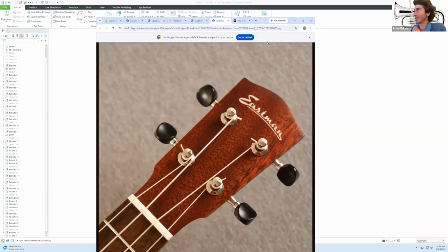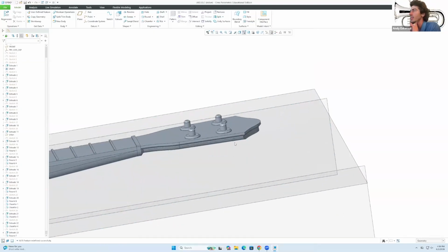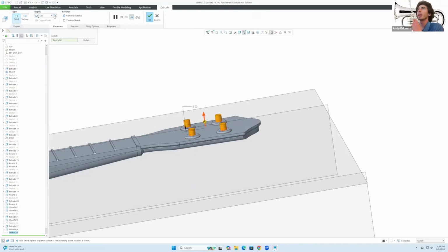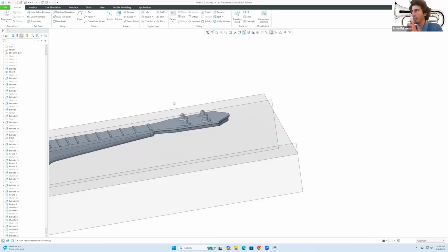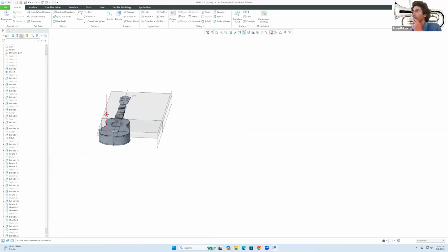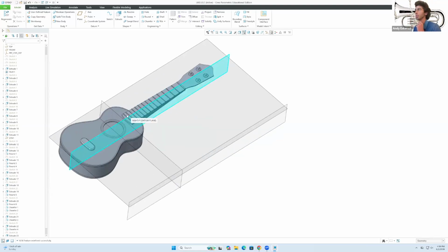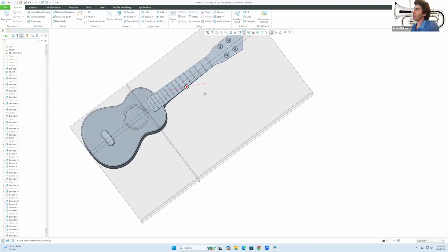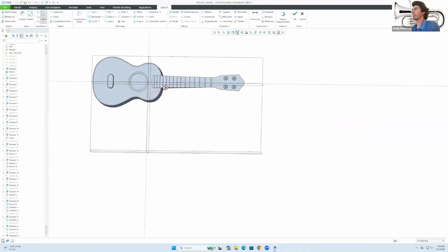So now comes the fun part. Even though there's just one last thing that I want to do, which is on extrude 23. I'm also gonna leave this again, and then I'll come back to that in a minute. So, how do we add the strings? Is the magical question in here. Well, what I'm gonna do right now is a sketch on this face in here.